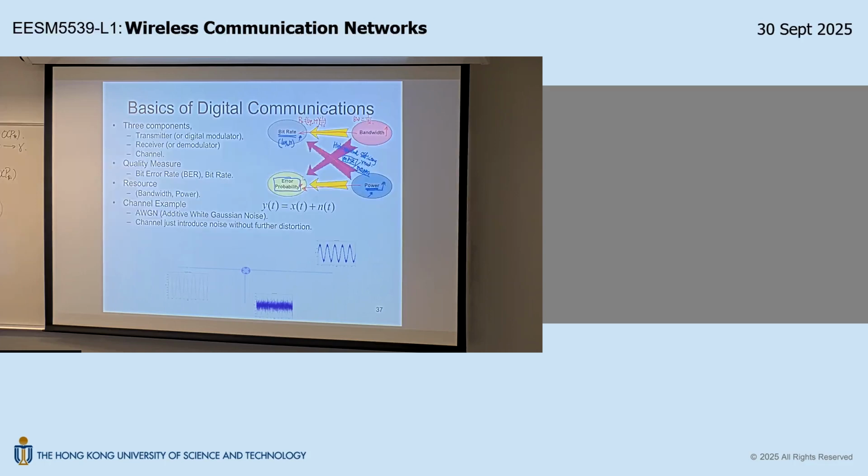Why high energy efficiency? Because if I do not need to reduce the error probability further, and my error probability is good enough, then by using this MFSK family, since the space is more spacious, I can afford to put the constellation points closer to the center. So I can reduce my transmission power to achieve the same error probability. So that's why this can bring me power saving.